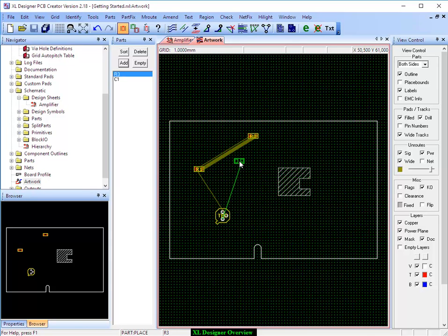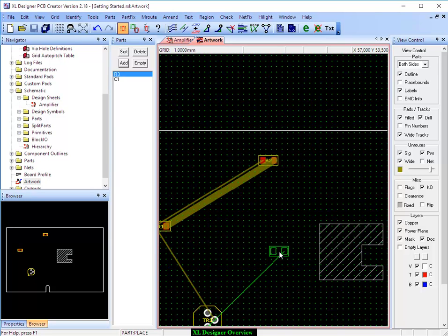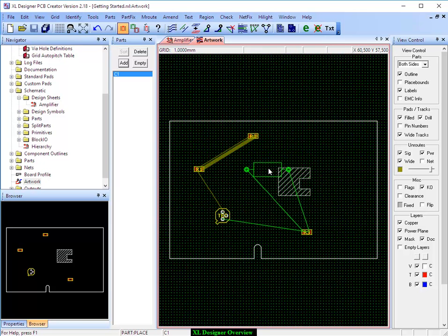As the parts are placed you see the interconnections appear, and you can see on this component it's obviously joined to a power rail because the connection is a lot thicker than the signal wires that were added. And then as we move the components around you see the connections jump from one position to another. As you move the parts you'll always get the shortest connection length between the connected pins, so you can get a good idea of where's a good place to drop the component. You can press the R key to rotate it, so we'll utilise all the space we've got.